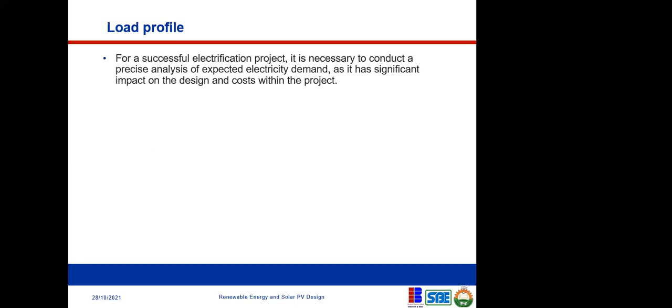So let us look at load profile. Load profile is critical when you're designing a solar project, especially when you're doing it for a large scale, maybe commercial purposes or any other purpose. It's very, very critical. You cannot do without a load profile because that will determine the size of your solar plant, or solar power plant, or whatever it is.